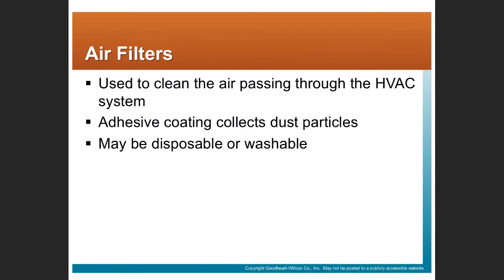Sorry, I lied. There's one more component here, that is filtration. One of the things that we want to do in an HVAC system is take some of the contaminants out of the air, right? Clean the dust and the dirt out of the air so we're not circulating that stuff around again. So we pass the air through some kind of media that collects those particles, that dirt. Those air filters, depending on their application, can either be washable or disposable. Nowadays, I think most filters are disposable or throwaway.